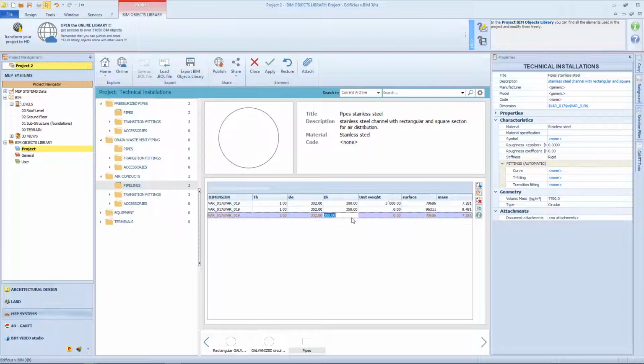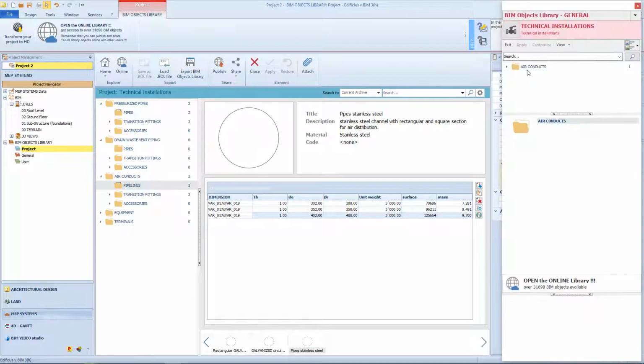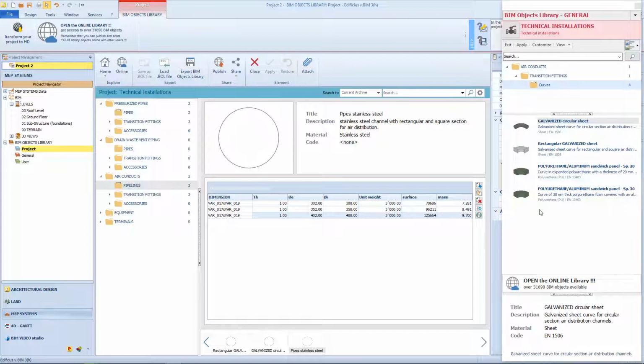The added profiles are customized, indicating their respective diameters and any other parameters. For a new pipe, you'll also need to set the automatic fittings feature, which needs to be compatible with the chosen profile and material. The relating libraries are then accessed, where the fittings to be attributed to the pipe may or may not be present, compatibly with the chosen profile.